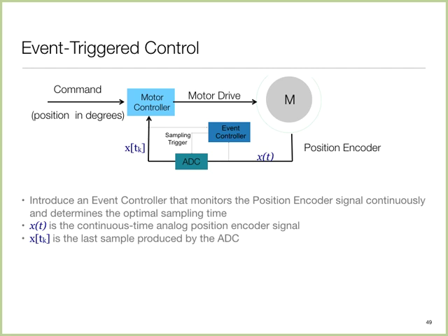So somehow on the analog side, I have to do all this logic about, has the signal changed enough. And remember, if I'm on the analog side, I can't do sophisticated things, right? Firstly, obviously I'm not allowed to digitize, because if I go to digitize, then I might as well have digitized to begin with. So if I purely want to do it on the analog side, then I need to perform potentially some complicated expression on the analog side, and then trigger the A to D converter based upon that. So that's one way we could do it.